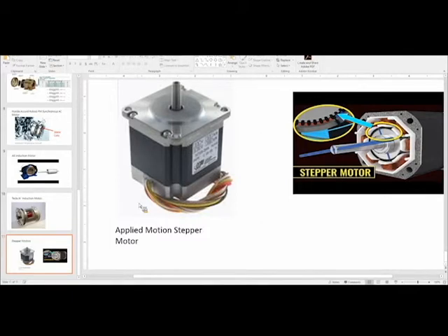And they have some sort of software module that controls all the electronic drives. You plug it in and you say, go to 25.8 degrees and it just goes there, right? The actual electronics are the complicated part. The mechanical part of this is really simple for a stepper motor. They're a little bit more expensive than DC motors, but they're great if you want to be able to control the position of something with high accuracy without any discussion of dynamics of the system. So they're great for class projects. They're great for a lot of industry applications where you want really precise control or fairly precise control.